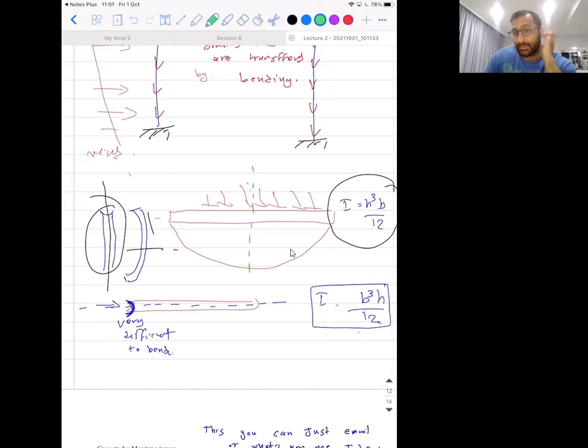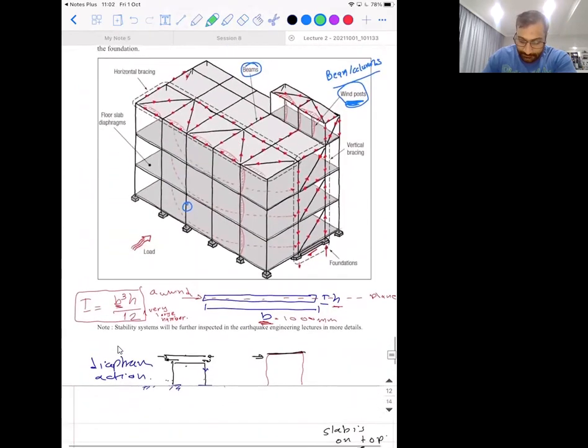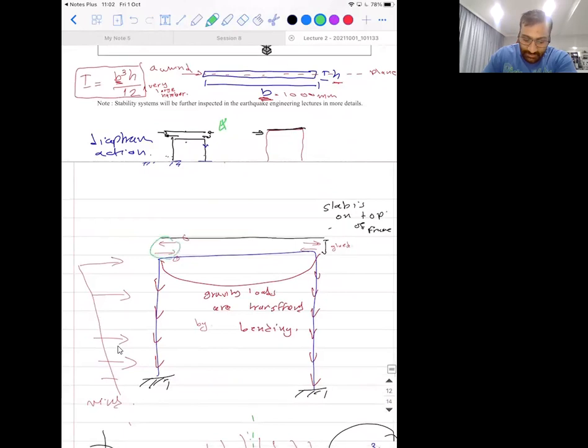If you're designing concrete buildings for earthquake or wind, concrete is very much preferred because, though it's heavy, you could make it a bit light. It would actually have floor diaphragm action, restraining columns and beams. We're going to talk about restraining conditions later, but for what it's worth, diaphragm action transfers the load, lateral loads, through shear to the structural members, like we see here, and here.